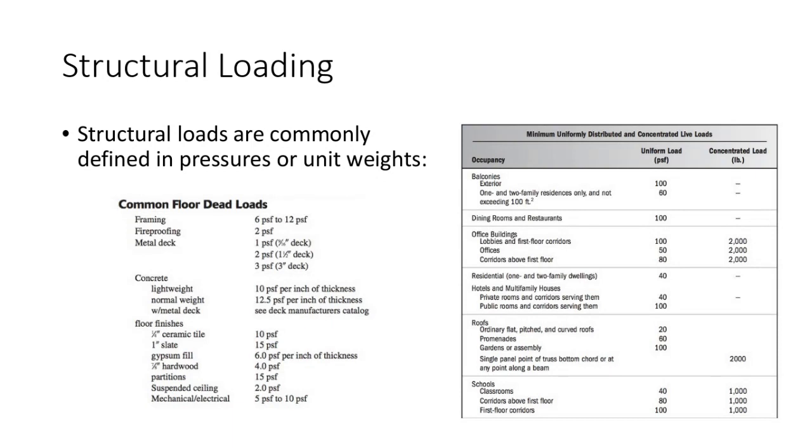We've got carpet. This is the second floor of the building, so under here, we've got the drop ceiling. We've got mechanical and electrical. All of those components that comprise the structure itself, we tend to refer to as dead loads. That's not always the only dead load on the structure, but the primary dead load that we as structural engineers need to deal with is the structure's self-weight. And the way that we spec that out is typically in terms of pressure loads.